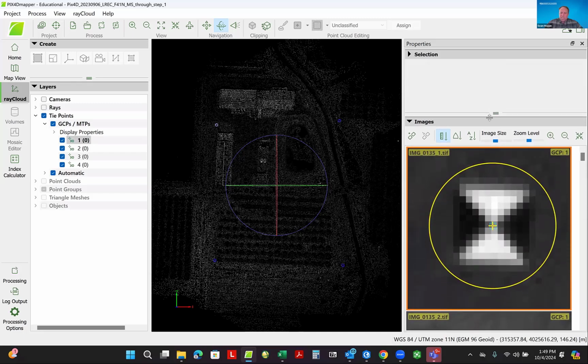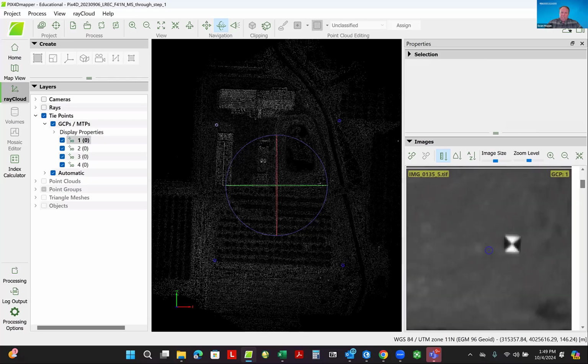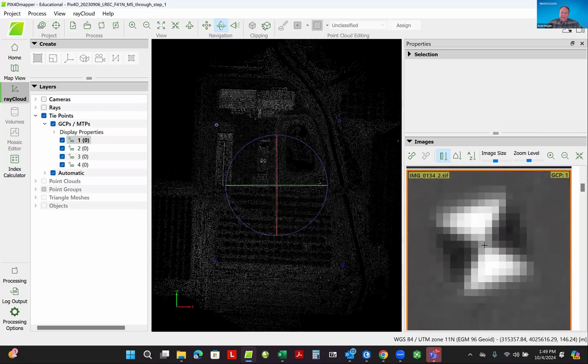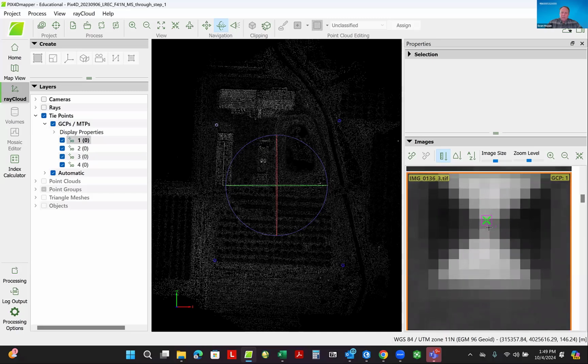What I can do is scroll this down so it's almost to the bottom, and then I can click down images till I get to, say, 134. Might even go to another band, and then add in. The directions would call for doing this same process for at least 4 positions. I recommend more like 5. You'll see a green spot appear once you've added in a couple of these ground control points.